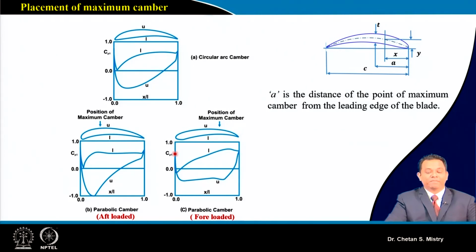That's what is happening on the later part of my blade. And in the same way, on my lower or pressure surface, I will be having flow acceleration followed by deceleration of my flow. So this is what we are looking for in the sense of half-loaded and full-loaded configurations. Let me tell you the recent trend, where people are defining this CP distribution.